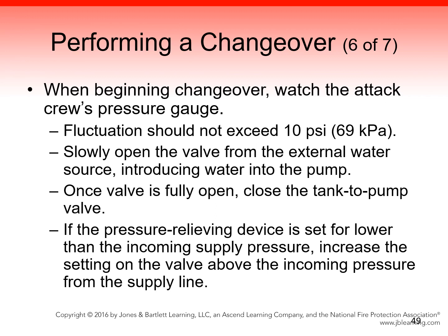At the beginning of the changeover, keep your eyes on the pressure gauge for the line that the attack crew is using. The goal is to ensure that fluctuation does not exceed 10 psi. Slowly open the valve from the external water source, which will introduce water into the pump. Once this valve has been fully opened, close the tank to pump valve.